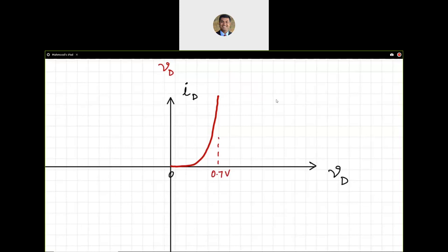And we have learned that for the diode, because we have that limiting voltage on the positive side, the voltage across that diode cannot go beyond 0.7. For practical experimental purposes, it might go to 0.72, 0.75, but it's never going to cross, say, 0.8. But for all numerical calculations, we will assume that it is 0.7. That's where it gets limited on the positive side.